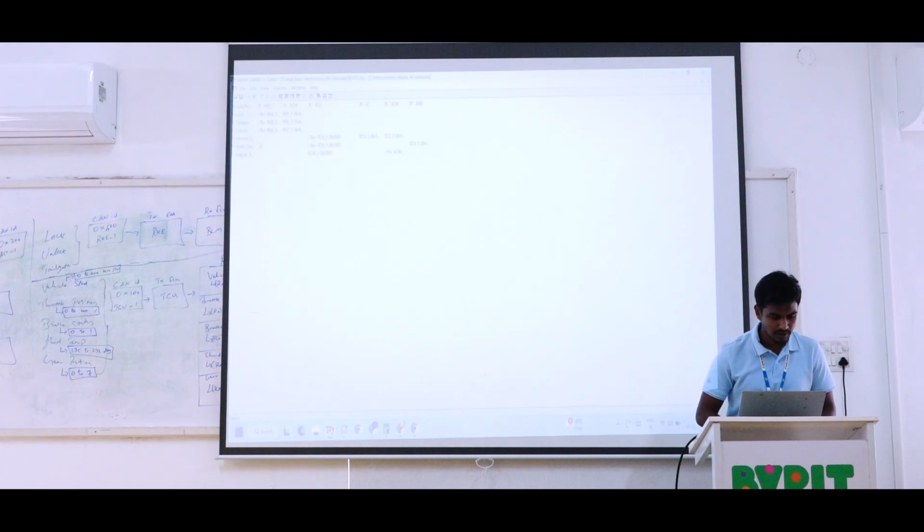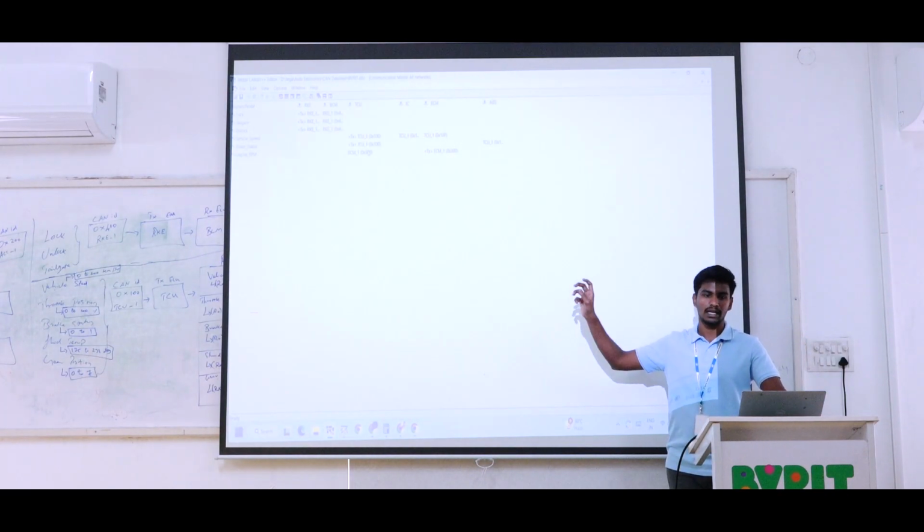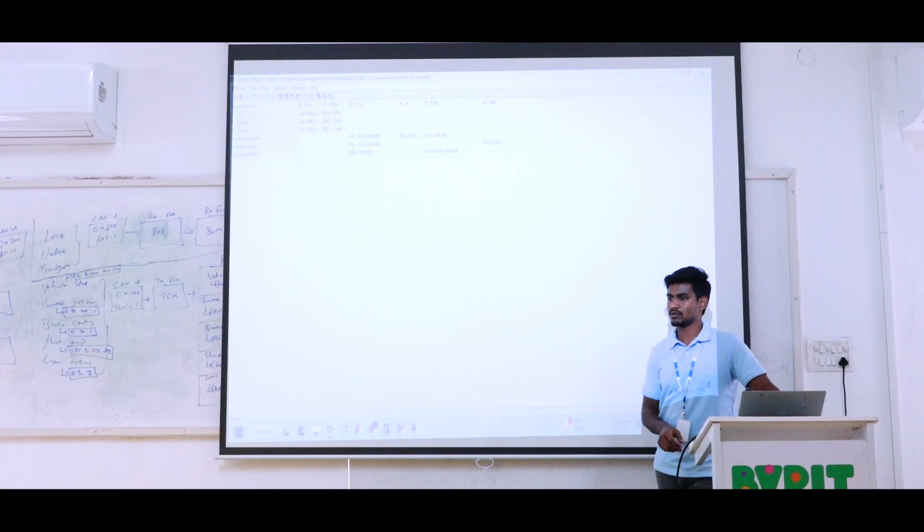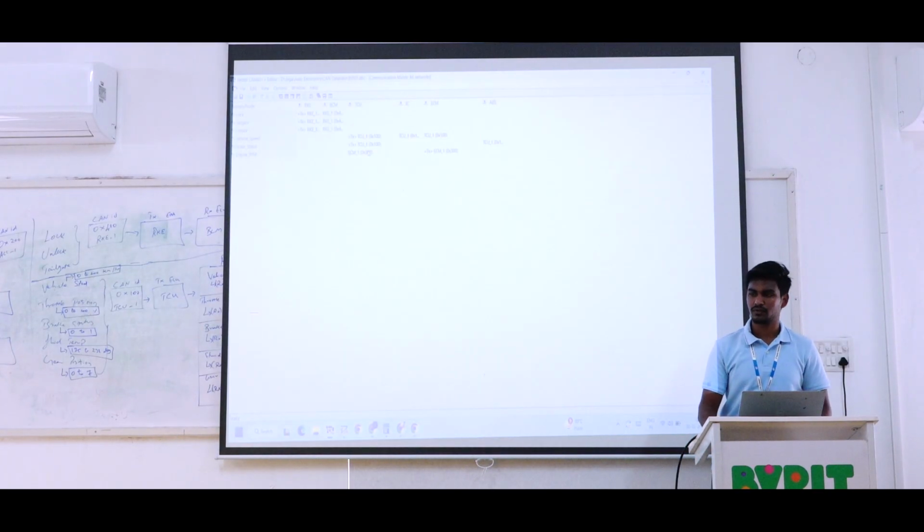Here you can see the vehicle speed is transmitted by TCM and received by the other two ECUs. Same as the engine RPM, which is transmitted by another ECU but received by TCU. So this ECU is able to transmit the values and also receive the values. So there is no issue with that. We can transmit and receive at the same time, based on the identifiers. Okay, so actually this is the overview of this CAN database.